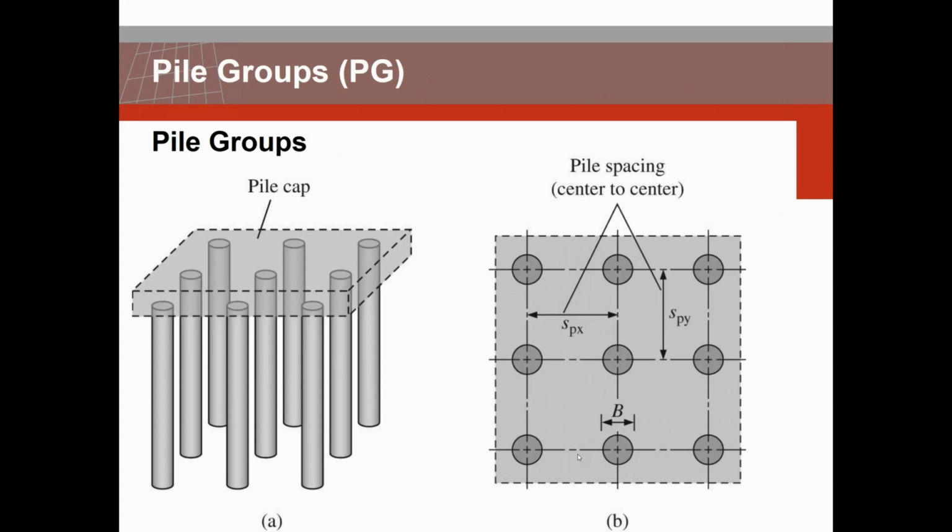Usually, piles are used in pile groups. Only in pile testing do you use a single pile. They are connected near the pile top by a pile cap. The design will involve determining the optimized design for the number of piles, the spacing, and the layout of the piles within the pile foundation. The pile cap mainly serves to distribute the load coming from the top to the different piles and to connect these piles to the upper structure.